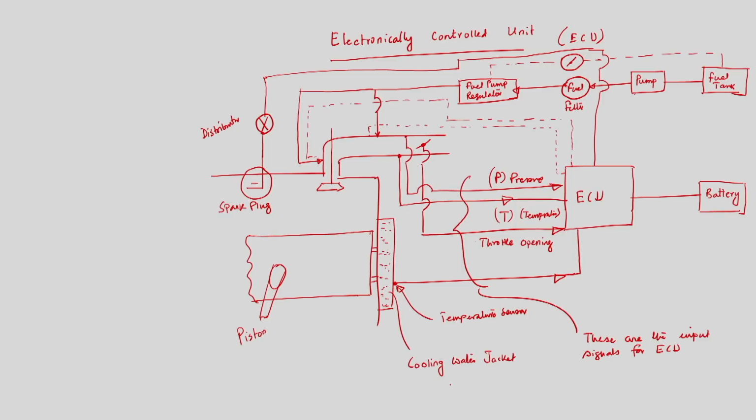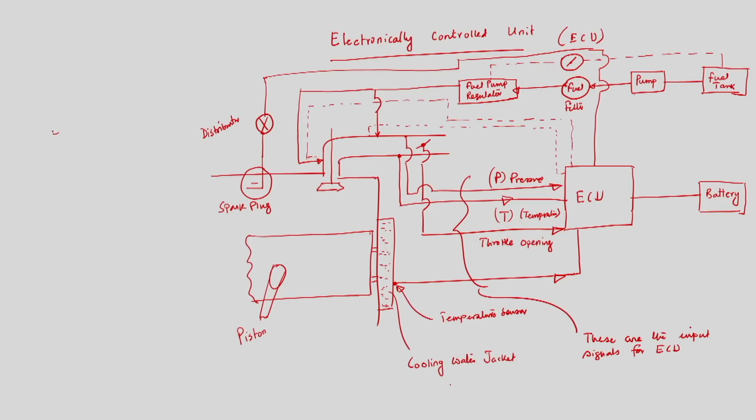We have an engine block sensor to maintain the water jacket temperature. The sensor is connected with the water jacket, we need to monitor the cooling water temperature. Why do we need to monitor the water jacket temperature? The latter is used to indicate the fuel enrichment during cold start and warm up. So, I am writing the primary inputs into the ECU.